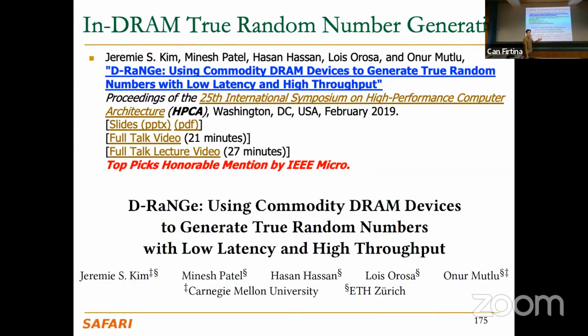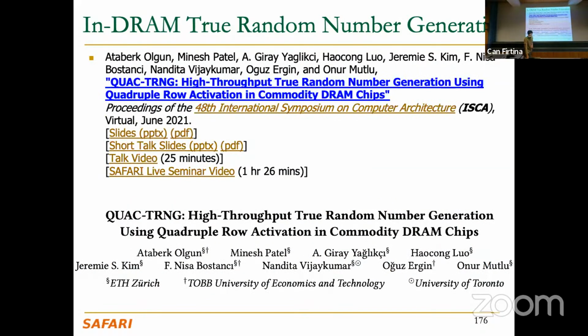But it can be very useful in computing systems: a true random number generator can be used for security applications, encryption, etc. This is another proposal, and this one was somehow inspired by the Ambit work as well. In Ambit we activate 3 rows and obtain a majority function. And probably most of you have thought, okay, what if you don't activate 3, you activate 2 or activate 4?